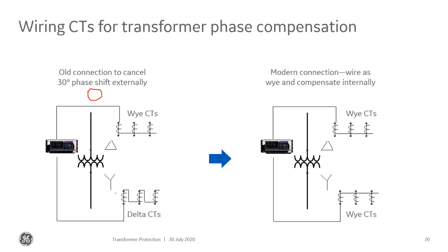The reason I've got that grounded Y connected to the transmission system is so that I can sense ground faults on the transmission system. Now that delta to Y conversion, it blocks that zero sequence current. That's great because I do occasionally have ground faults out on the transmission system, but I want to block that zero sequence current from my generator. I don't want that to damage my generator. And I can block that with that delta to Y conversion.